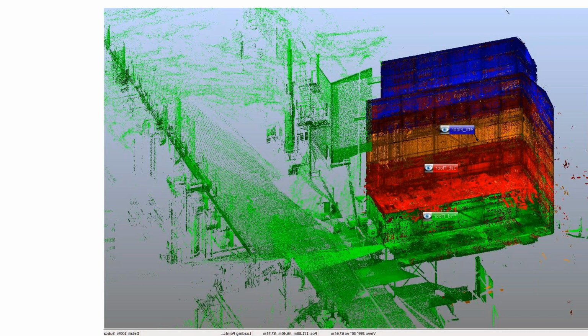so that we're able to scan a particular area. Say we get 60 scans roughly per floor, register them all together, lock them into a cluster, and then move on to the next floor. And then once you've done all 4 floors, for instance, with this particular job, all we need to do then is just register 4 different clusters together. It makes the whole job so much easier to register.